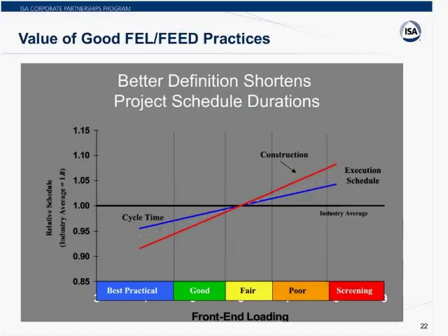It really depends on what kind of hazards you have. We would typically do a process hazards analysis, a PHA, and with that PHA, we would identify if there are hazards of special concern. We might do a layer of protection analysis, and if the risk was really significant, if there was the potential to kill a lot of people in the community in an incident, then we would probably do some detailed consequence analysis and fault tree work.